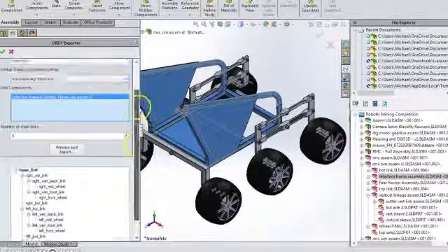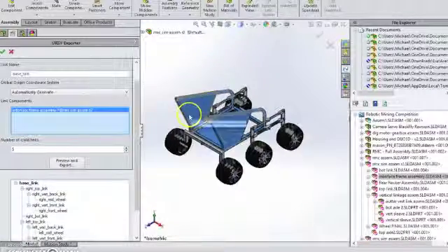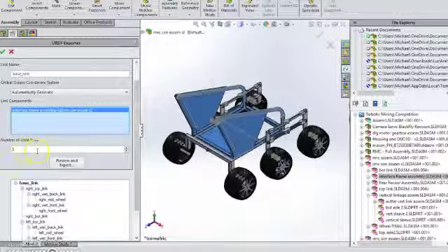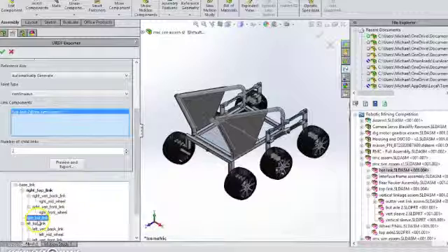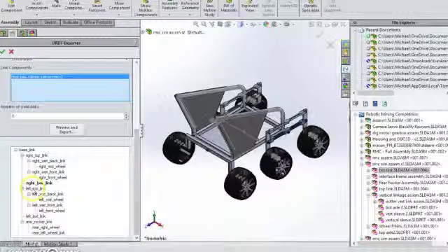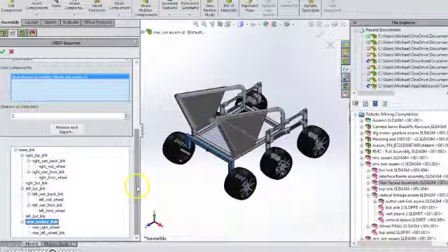In this export, we have the base link, which represents the central chassis of the robot. It has 5 children. The URDF is structured as parent links and child links. So this base link is the central parent link, and from that all other links branch out, like the tree structure we mentioned earlier. Direct children from the base link include the right top link, the right bot link, the left top link, the left bot link, and the transverse bogie, which we named the rear rocker link.